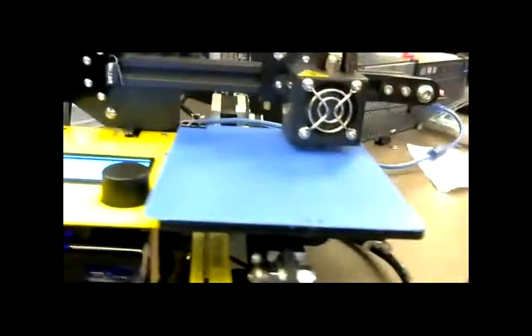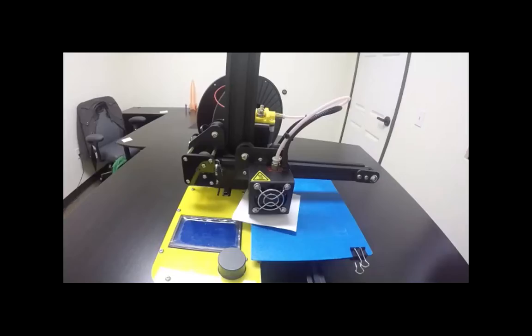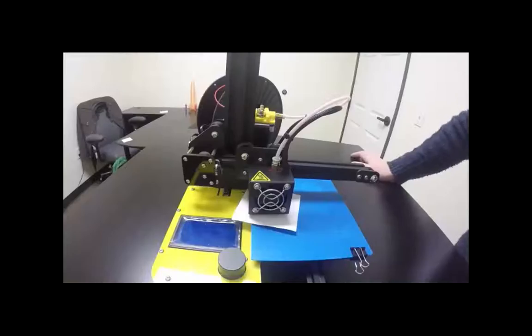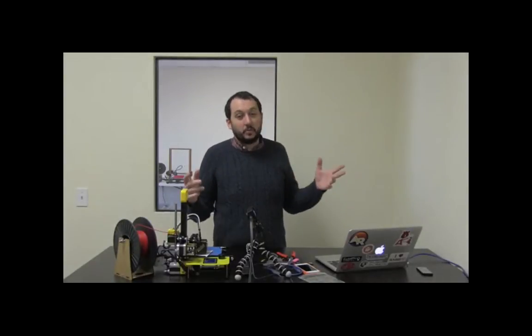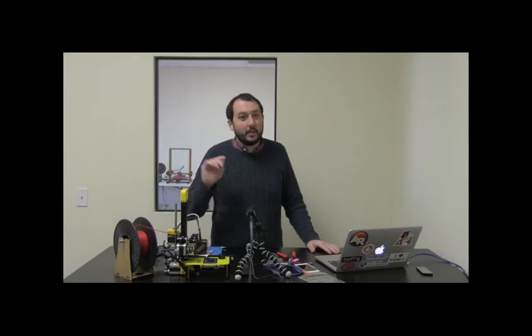So the inside one, which is right here. Yes. Yeah, that's the one that's kind of tough to get to. Let's push it down a little bit though, so you can slide that piece of paper in there. And this is really 90% of different 3D printer problems, is making sure that the build plate is level. It's a huge part of it. So once you guys have that figured out, you'll be good to rock.